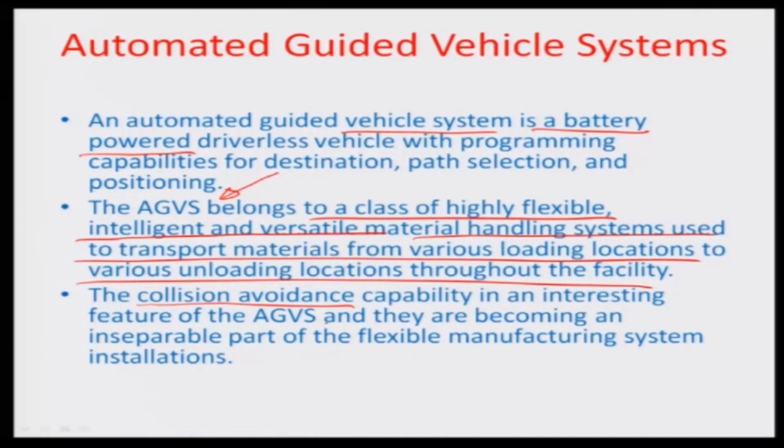So, although it is not a complete robotic system, you can say that it is at least a partial robotic system which would have some intelligent capabilities like sensors, etc. built in, and the directives can be given to it through a path which can be laid out either as a fluorescent light path or paint path, or as some kind of electronic assistance by an underground cable, so that it can help to move the AGV in a particular direction from time to time.